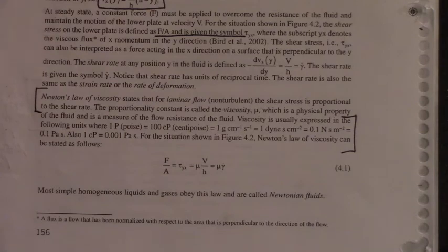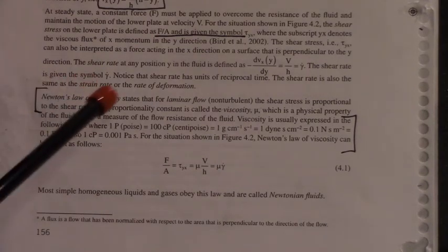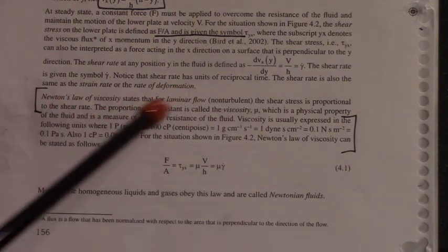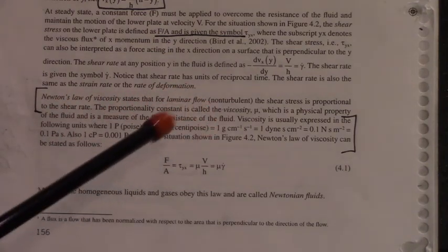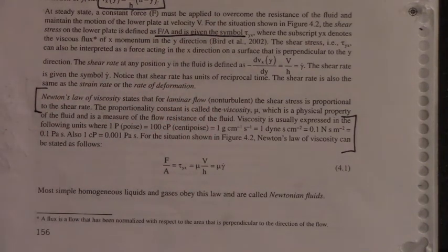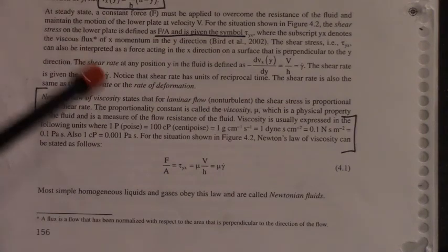And this little thought experiment that we went through gave us a logical way of coming up mathematically with what we mean by viscosity. And viscosity represents then the flow resistance of the fluid. So a fluid that has much higher viscosity is going to have a higher slope. It's going to take more force to deform that particular fluid.